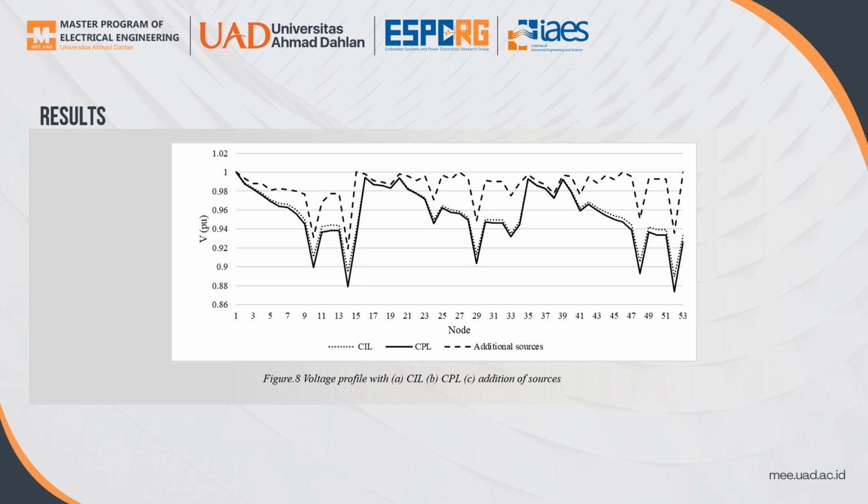In the second case, we have added 26 PEV chargers to random residential loads, which caused voltage to cross beyond the standard voltage limit at 4 places. So the voltage violation is more frequent and can get adverse with more loads on it. As mentioned before, adding distributed energy resources and having local energy sharing arrangements will significantly improve the voltage profile. So we have added 4 additional DERs in the system. Improvement in the voltage profile has been observed here.